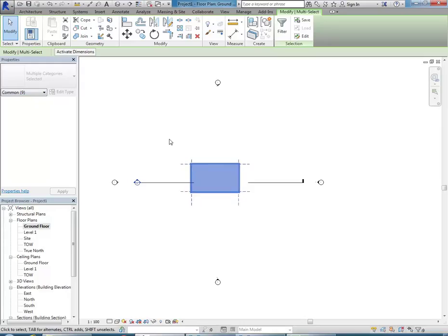What I'm going to show you there is that you can use the arrows on the keyboard to nudge that around and just try and get it centred within those views, because again, they're your elevation views, those 4 views around the outside, using the arrows on the keyboard. Can you move it up and down? Yes. And if your section lines are wide, that's okay, the length doesn't really matter. We'll fix that afterwards.